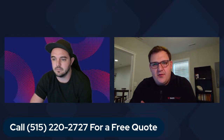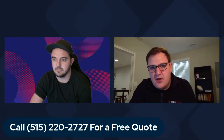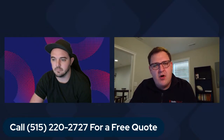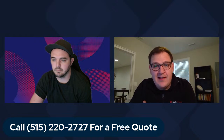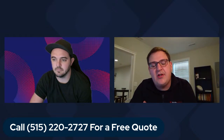Yeah, I always tell folks that the gateway box is built for in-barn conditions. So it's going to be dust-proof, moisture-proof. However, I would always recommend putting it near where your ventilation controllers are. In most cases, there's a specific control room or office where a lot of that electrical stuff is housed. And so that's where I would recommend putting the gateway box, and just keep it in as clean of an environment as possible.